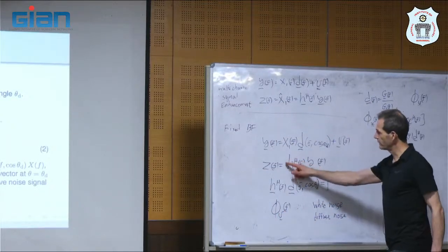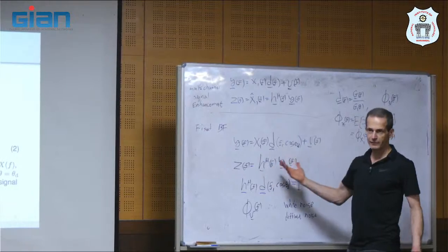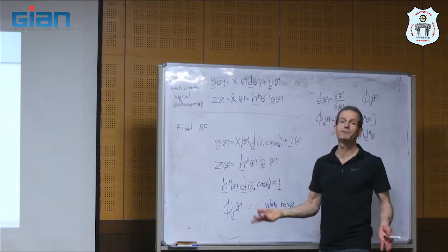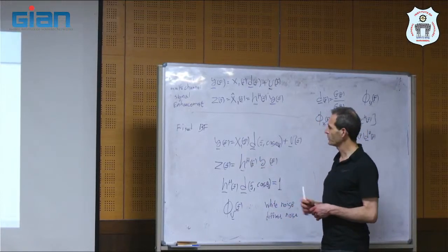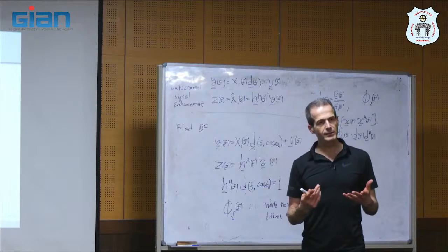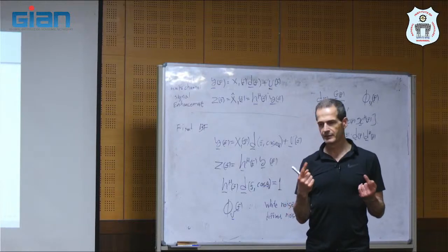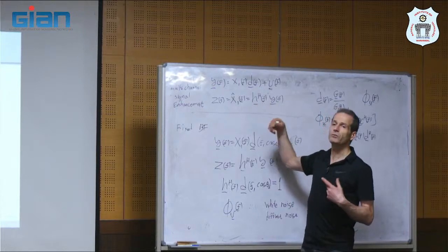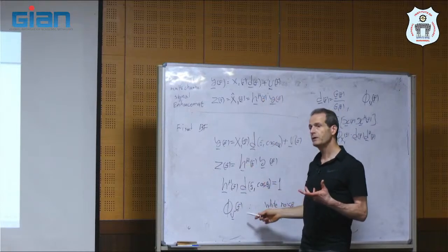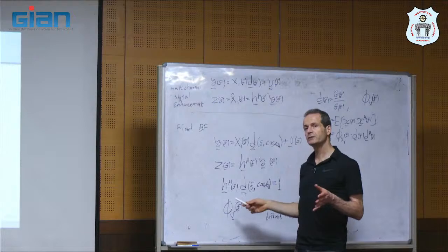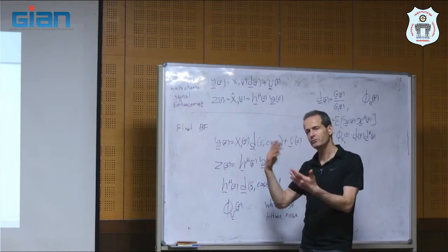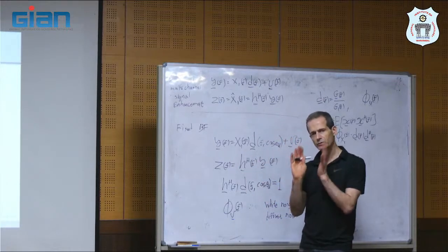So even here, when we apply the beamformer, instead of filter, with signal enhancement, we call it filter. Here, we call it beamformer. It's just a name, but when people say beamformer instead of filter, it means something. Filter means that we know information about the statistics of the signals, the desired and the noise. Beamformer means that we don't make assumptions about the environment. If we make assumptions about the environment, we will talk about adaptive beamformer. We will move on. But first, I want you to understand.